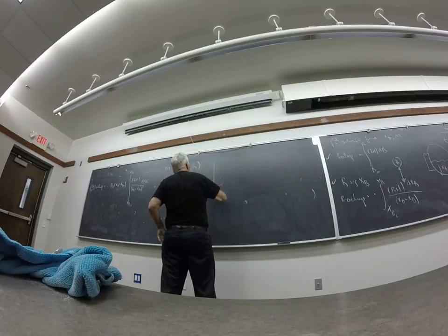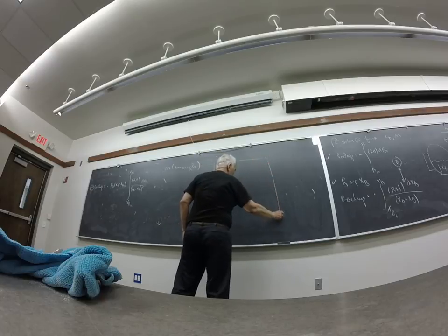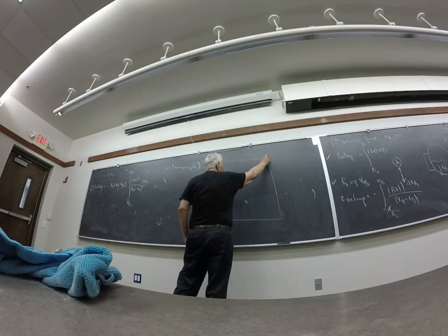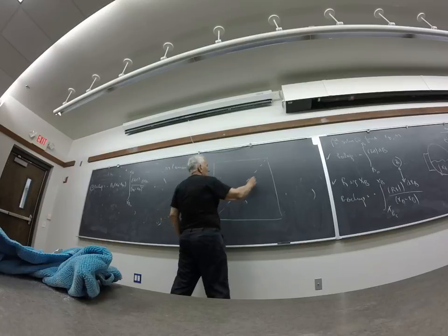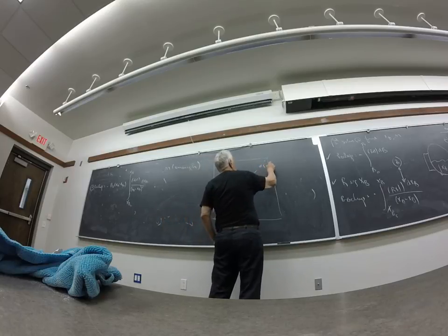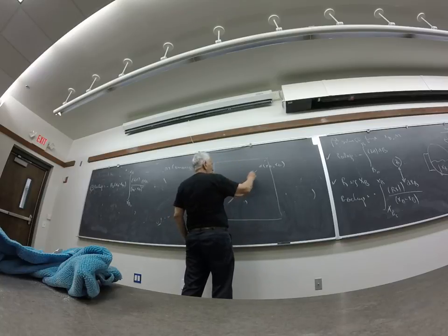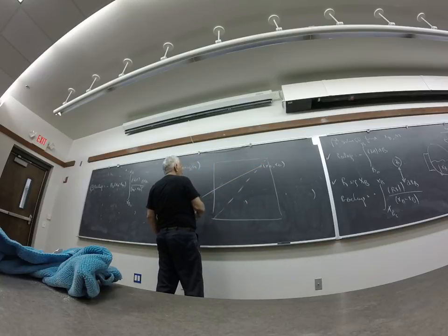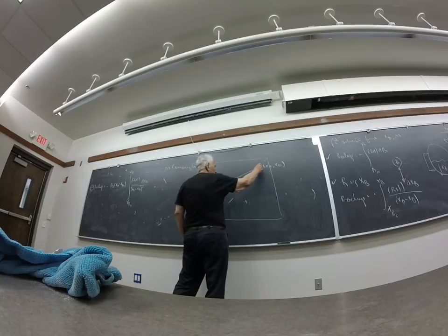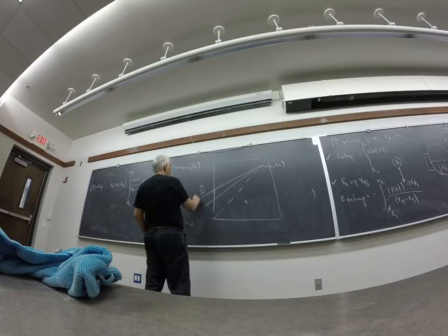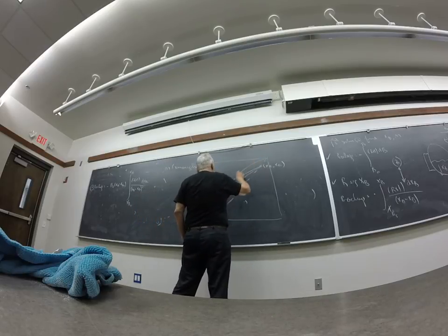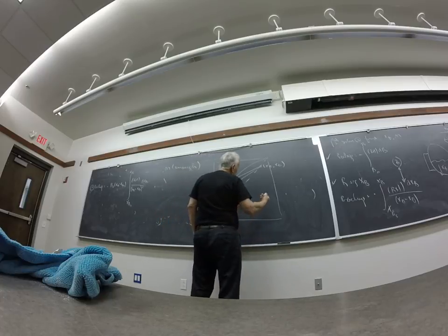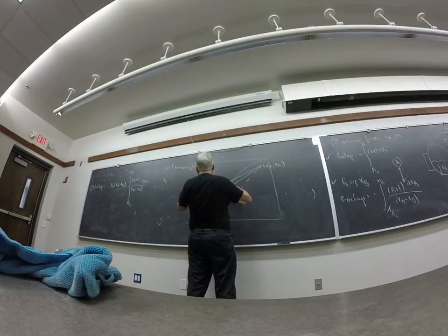So under the assumptions that we've been making, this might be the xd you're shooting for. And at that xd, you can take a look at r. Here's a line of slope r over r plus 1. You can take a look at another r. Here's a different r over r plus 1, and so on. You can put the equilibrium curve in wherever it is, and you can say, okay, at this r,